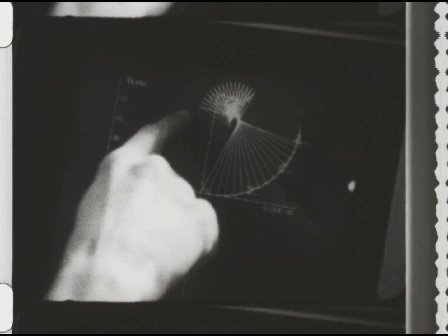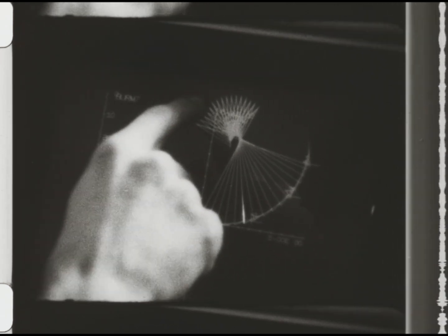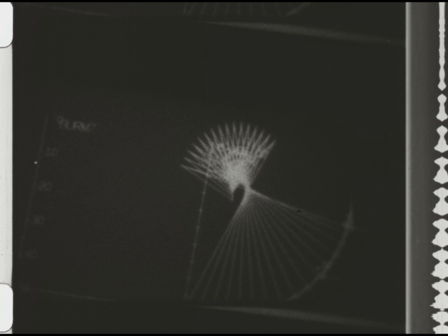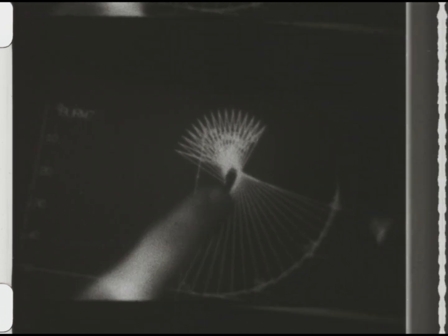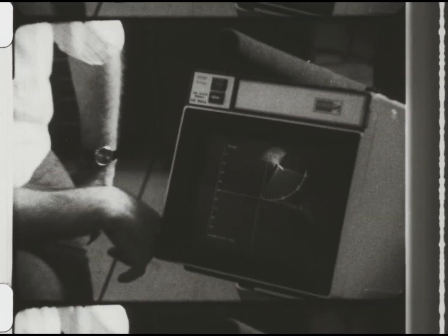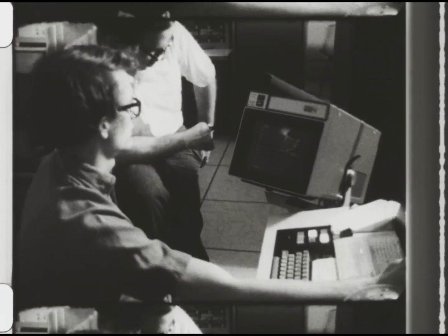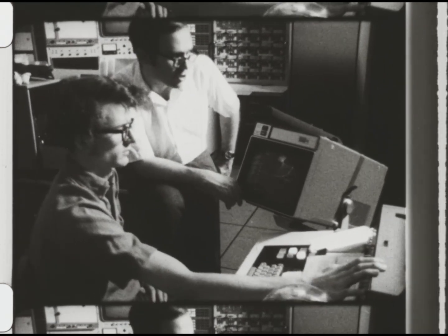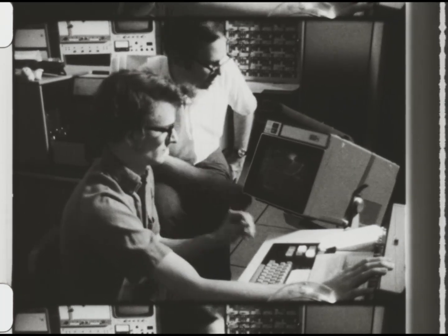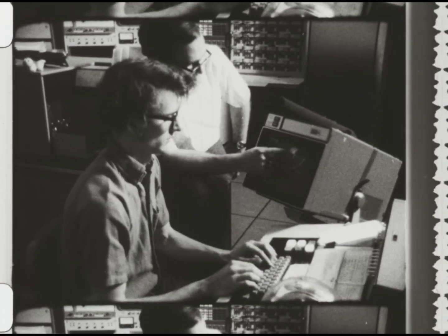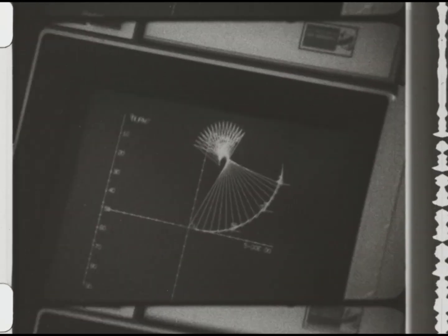Driving from the crank, you can tell this because of the equal increments of this crank going through here. It's marching along at equal increments and moving this coupler plane, which this line is in the coupler plane, and this, so the short line segment through the design positions. If he wants, this program allows him to interchange and drive from the slider rather than from the crank. The slider's a little bit unclear in there because it's buried under all those lines.